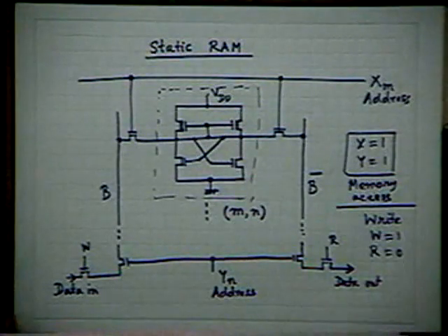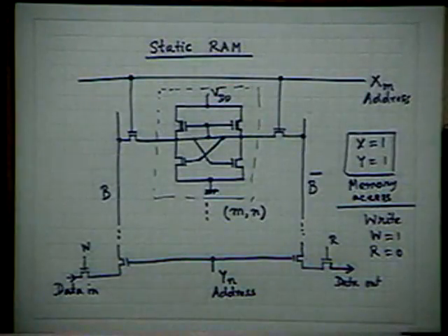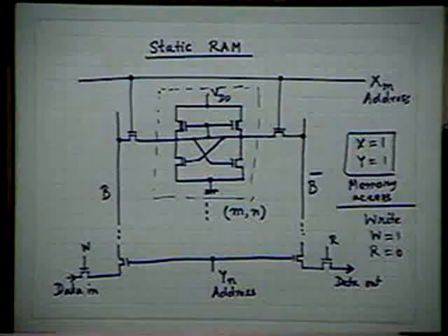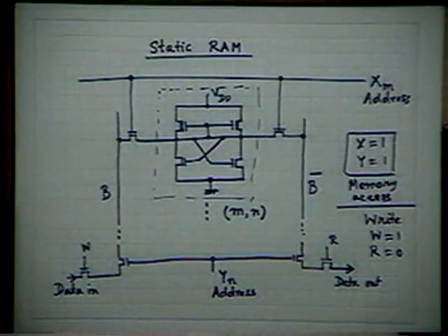The C's are so small that charging and discharging may be very fast. It is the bit lines which become the actual culprit compared to the individual memory elements, because they are sluggish and store a lot of charge. You are trying to change them, but they do not change quickly. So you have to do something so that this charging and discharging can be done very fast.